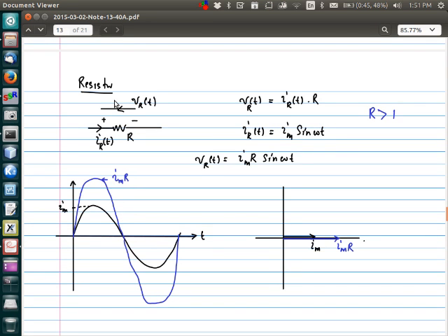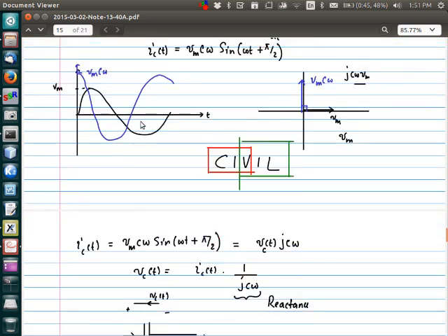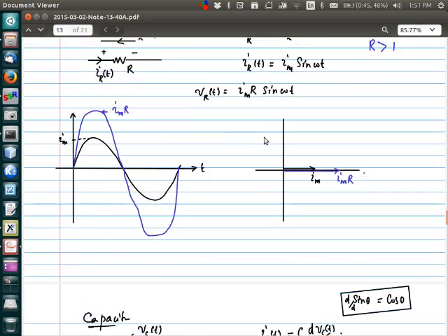And then from that, I brought you into finding out AC equivalent circuits for the resistor, the capacitor, and the inductor. And this little thingy that I drew here is what is called the phasor diagram, which means if you look at voltages and currents in the circuit, the plot of its magnitude and the phase is called the phasor diagram.